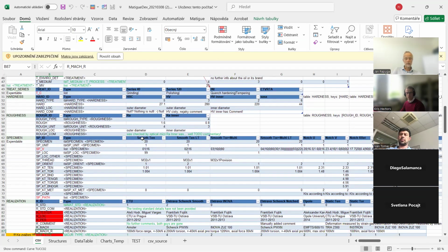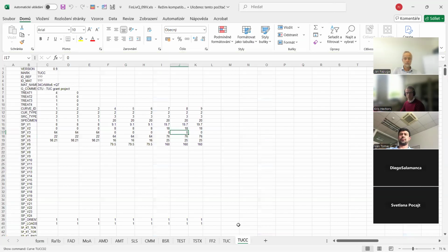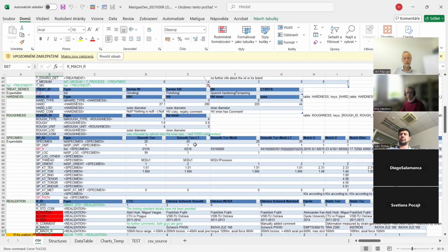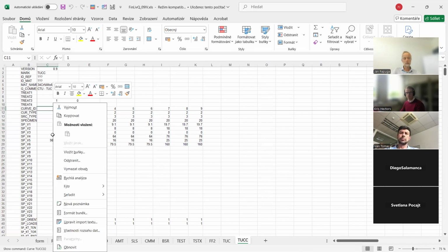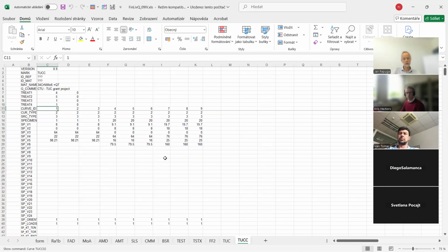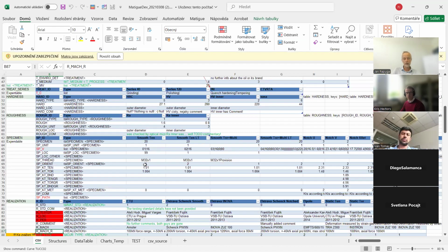And again, it's separated into groups. What I showed you here, for example, we have 3 different types of specimens. One is full bars with the same parameters. Then there is a hollow bar with the same parameters, and another hollow bar specimen, but with a much bigger cross section. So technically, this can be replaced here, so that the person who is aggregating the data will define just one configuration, a second configuration, a third configuration, and once they are there, I can relate it to any further fatigue curve.